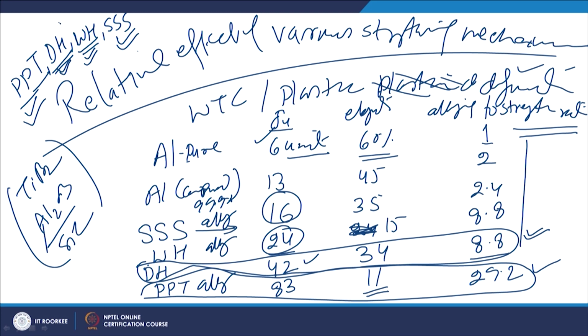So, whenever there is a loss of precipitates or the dispersoids present in the aluminum alloy, and the development of either the work hardening effect or the solid solution effect, their effectiveness is limited. That is why we will notice, either during fusion welding or due to deformation, that loss of precipitates or loss of the dispersoids will lead to softening. So, despite the refinement and the solid solution strengthening, in the case of precipitation and dispersion hardening alloys, there is a loss of strength and hardness. This is the net effect for the aluminum alloys and the magnesium alloys which are precipitation strengthened.